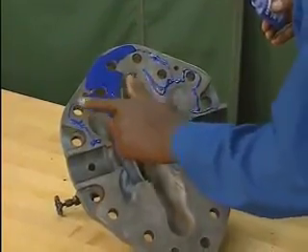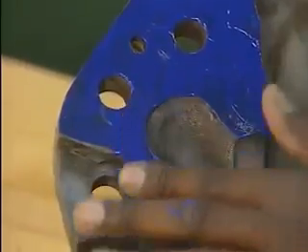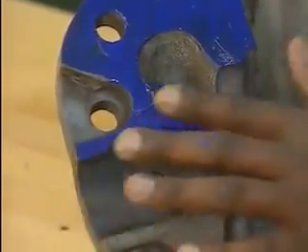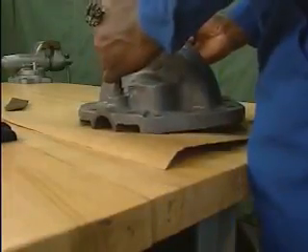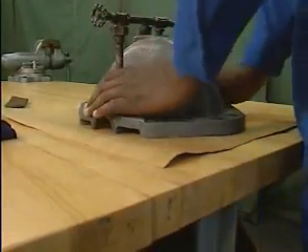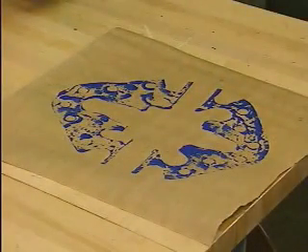to the gasket material. In this example, the mechanic coats the sealing surface of the upper half of the pump casing with a type of dye called bluing. The mechanic places the upper half of the casing onto the gasket material and presses down firmly. As he carefully removes the casing, some of the bluing transfers to the gasket material, creating a pattern.